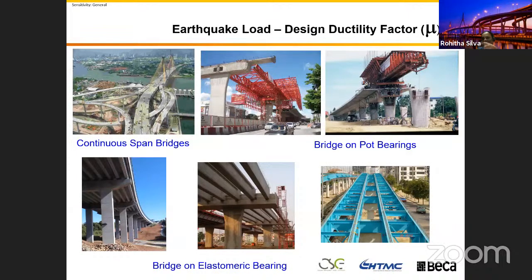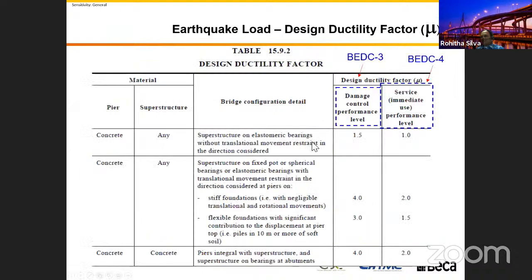Because of that, with this ductility factor, you see our probability factor or the importance levels, with that one we increase the earthquake effect. With ductility, we can go in the opposite direction. So the better the ductility, the more you can redistribute your load. That's the way you can understand it as structural engineers. And then all these factors are related together in the later stage.